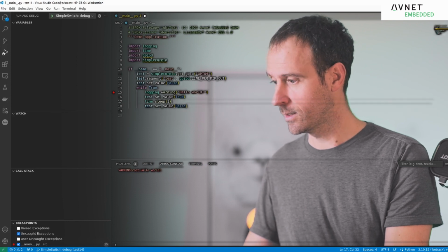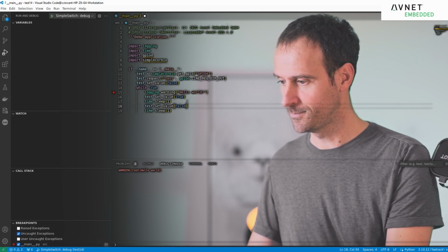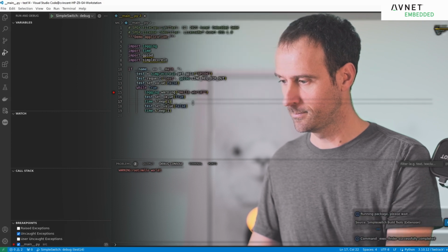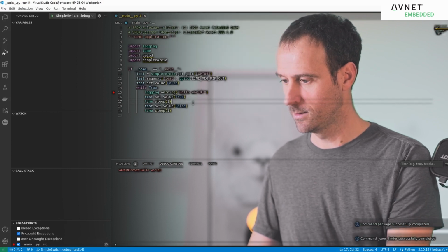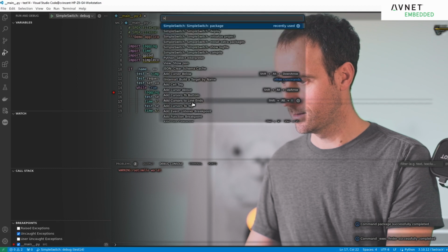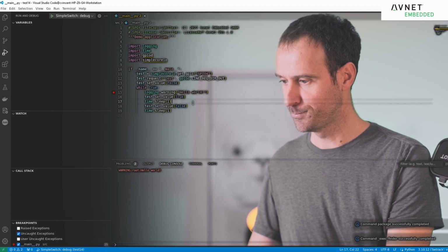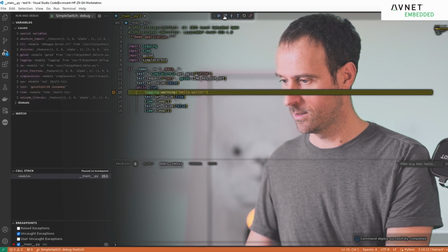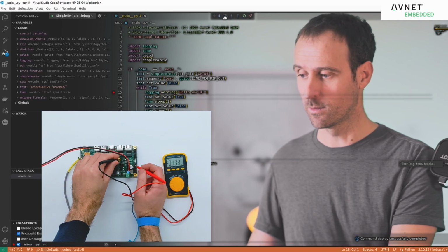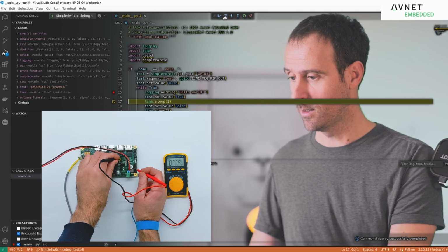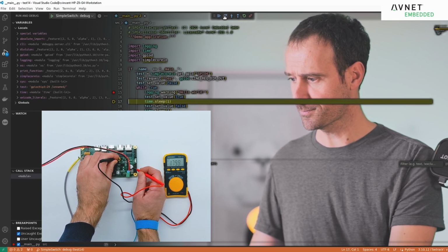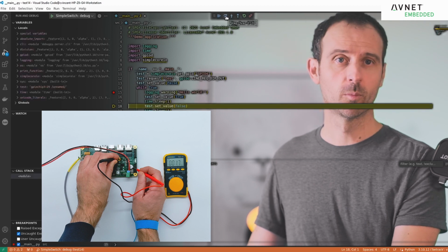And then we can finally hit F1 and repackage, and then again and redeploy. So now we press F5, we start the code, and we can see that on the feature connector 3, pin 11, if you check with the multimeter, you will see that the value is changing. Perfect. First part of the project is done.